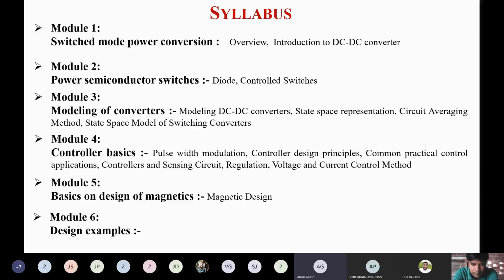So here the logic will be like that. If the control signal is towards the high position, the pulse width will be less. That means your control circuit is instructing the solid state device to turn on for a lesser amount of time. So if it is turned on for less time, what happens? Directly the voltage will gradually be reduced. That's the way you are maintaining the regulation.